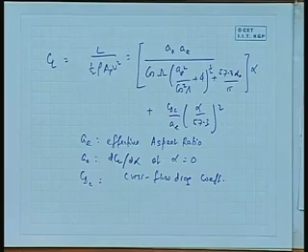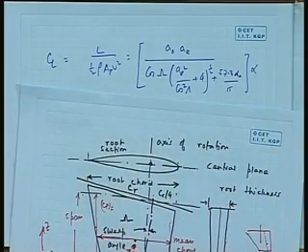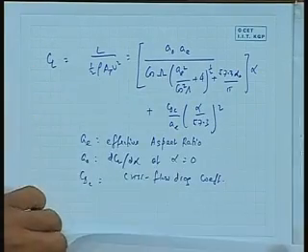Etc., etc. Let me not go into so much detail. The question that remains is something like this. Let me see from the end. I have a rudder here. I want to find out, if I give the rudder angle of delta R, what Y force will I get? Because the formula of turning, Y delta R, was the rudder force. So to know the Y force, I have to find out what is my lift and drag on the rudder.